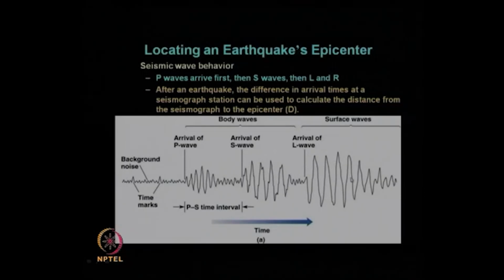But from the typical velocities, the S wave crustal velocity is about half of that of the P wave. P wave typical crustal velocity is about 6 km per second. For S wave it is typically 3 km per second. Due to this large difference between their crustal velocities, their arrival times can be obtained distinctly on a seismogram.